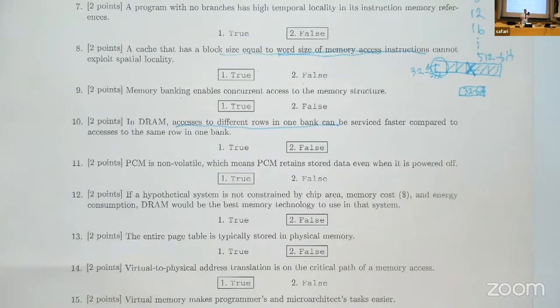That means you have a row enabled. Basically, this access pattern will have a lot of row conflicts or bank conflicts. This means that you enable a row, you spend some time to satisfy the latencies, the timing parameters, and then you pre-charge that row, you enable another row, you pre-charge it, enable another. It's like a double-sided RowHammer attack, if you remember that.